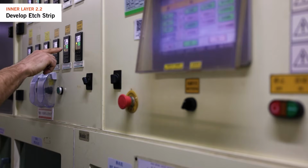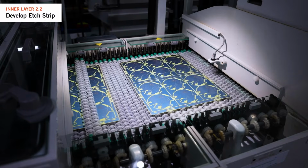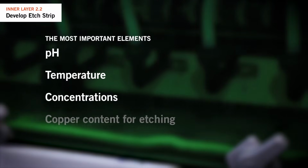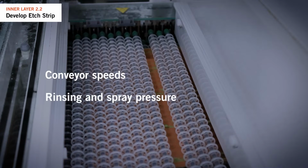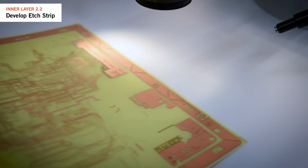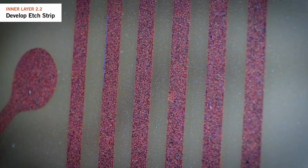Controlling the process poses significant challenges. As with all of the chemical processes, we must have tight control of the many elements relating to the chemistry: pH, temperature, concentrations, copper content for etching. And we must also manage the other elements such as conveyor speeds for different copper weights, rinsing and spray pressures to maintain precise etching rates. The goal is to remove unwanted copper without affecting the desired circuitry by etching either too much or too little. Higher technology factories often use vacuum etching lines for better control and minimal variation from the top side to the bottom side.